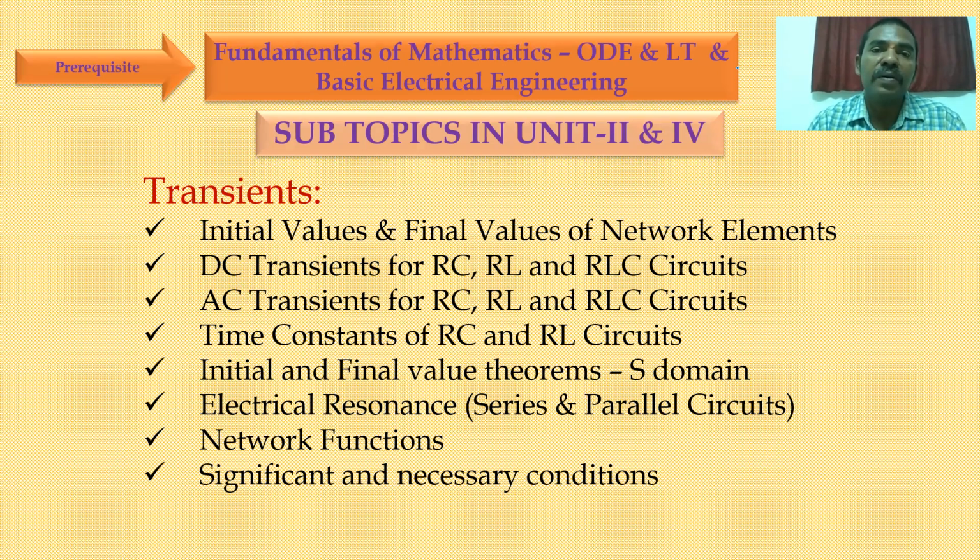If you substitute the numerator equal to 0, then you can get the zeros of the equation. Those roots are zeros, and if you substitute the transfer function as infinity, you can get the poles of the equation. So while you are plotting the zeros and poles in the S domain, you can go for the stability. So stability of the system also we are studying at the same time. What is a magnitude plot and what is a phase plot also we are studying in this unit.